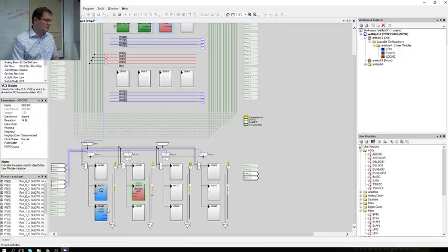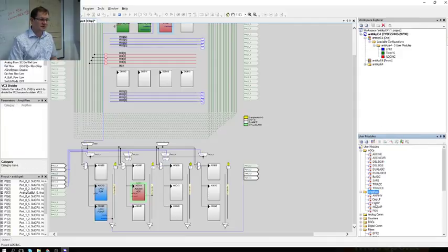So I think the correct way would be to move it to analog bus port 03 if it's not used otherwise. Then you can take the port 03 signal, for example. We'll put a gain of 1. You can connect the amplifiers, BGA.